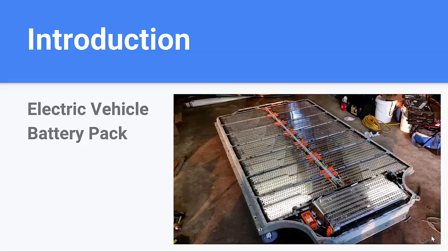There are 12 modules in each pack, a compressor with cooling system and lines, a bus bar, which is connected to the modules, and then a rubber buffer along the spine, a high voltage connection next to the motor, a main cooling system, a mother BMS, fire retardant lines, the top, and then a plastic casing that goes on top of the aluminum.